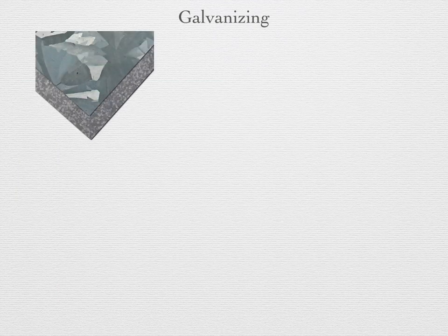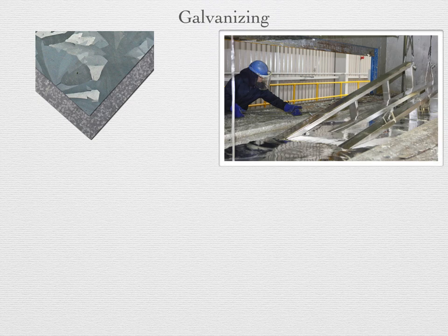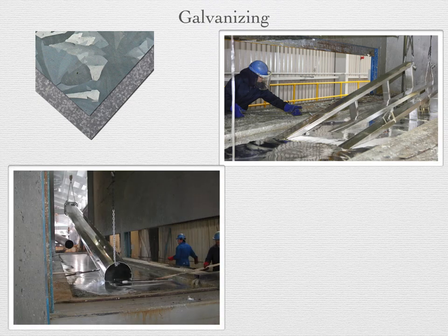Steel can also be galvanized by dipping a finished piece in a hot zinc bath. A layer of zinc metal crystallizes and binds to the substrate surface. The distinctive crystalline pattern that results readily identifies such material. The zinc layer acts both as a barrier layer and as a cathodic protection layer. Much construction steel is galvanized.